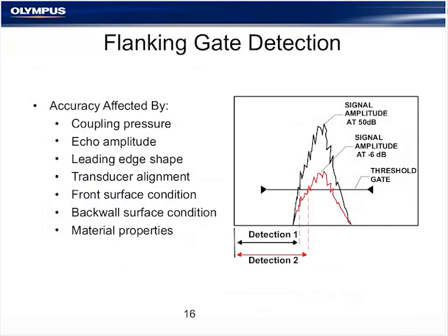Now, the detection algorithm, I mentioned before, Olympus has a very specific way of measuring repeatably and accurately the backwall reflection from a dual transducer. And there are actually two factors involved when we look at the comparison between this automatic thickness gauge detection algorithm and something more standard on a flaw detector. The first has to do with flank detection or edge detection on a flaw detector. The graphic that you see here indicates a fairly common signal that's returned from a dual transducer from corrosion, and you'll see that there's a gate that's set to approximately maybe 20 or 30% screen height.